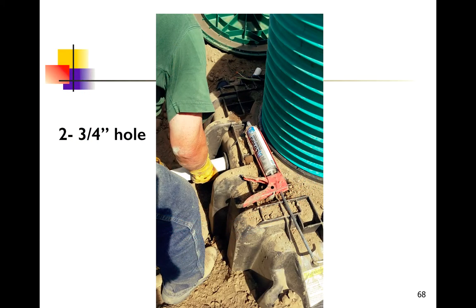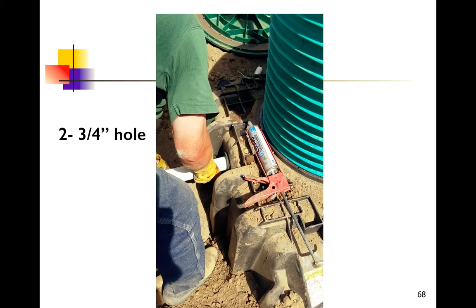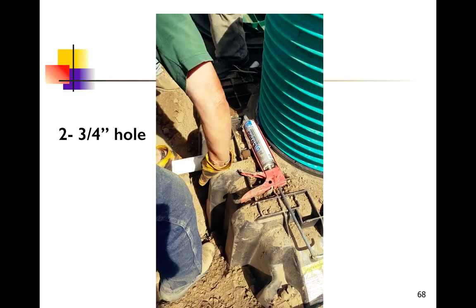If you happen to use an Infiltrator or a Roth tank, you can go ahead and use the larger 4x2 tank adapters that we provide, but you will need to have a 5-inch hole saw to use the grommets that will be needed for this tank. Otherwise, you can use the smaller grommets that they provide for a 2-inch pipe. You will need a 2 3/4 inch hole saw, and then about a 1 foot long piece of 2-inch pipe.